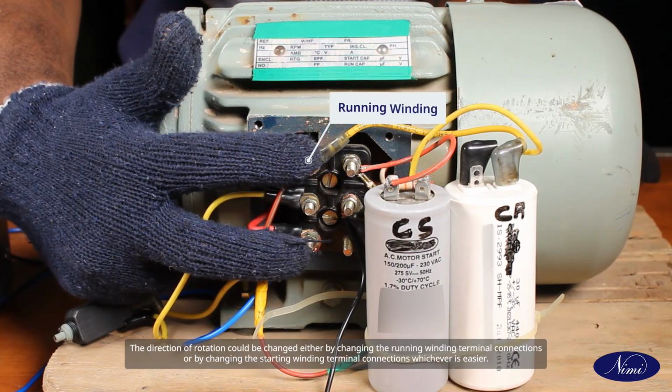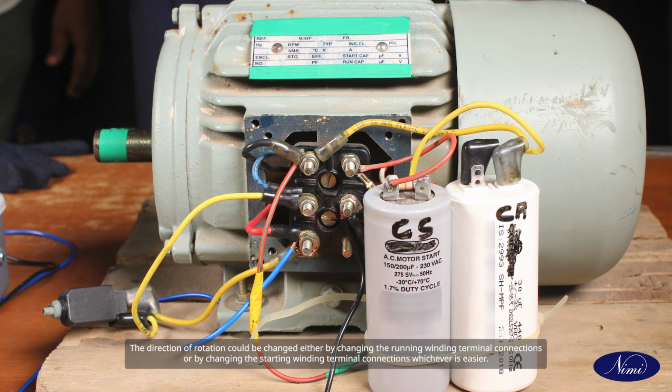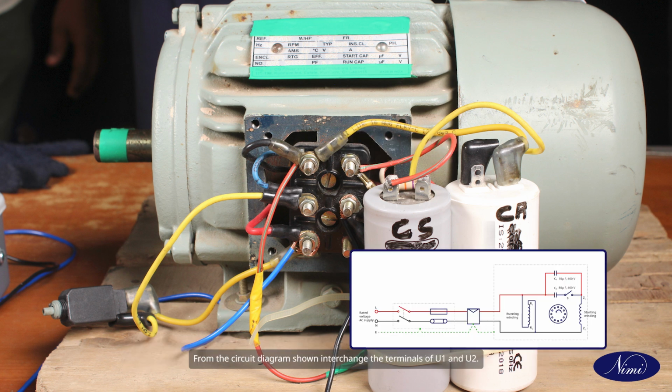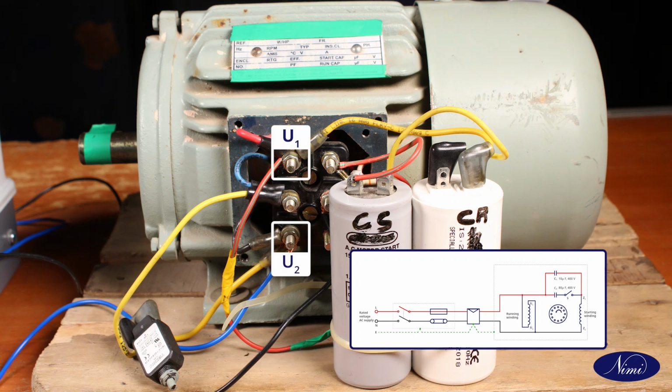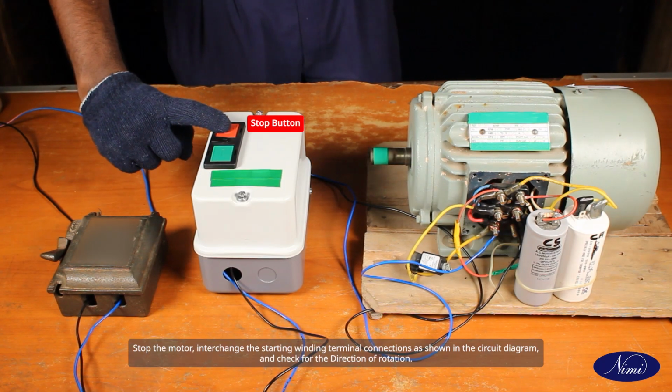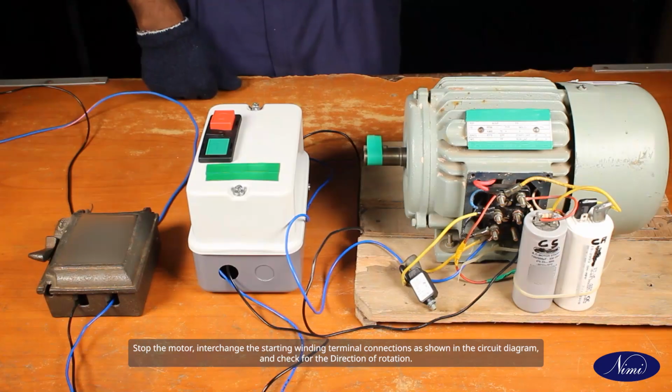The direction of rotation could be changed either by changing the running winding terminal connections or by changing the starting winding terminal connections, whichever is easier. From the circuit diagram shown, interchange the terminals of U1 and U2. Stop the motor, interchange the starting winding terminal connections as shown in the circuit diagram and check for the direction